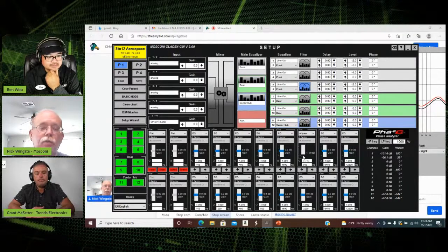There's a lot of papers written about all-pass filters, and they'll give you an idea about what works and what doesn't work. But I can tell you a lot of times, if you've got an up mixer like this thing does, and you've got a center channel working, and you're trying to get the left mid-range to align to the center channel, you use an all-pass filter.